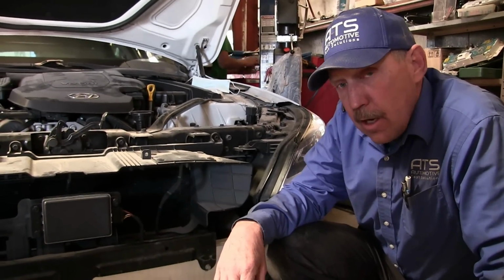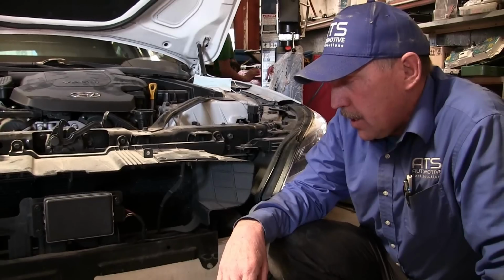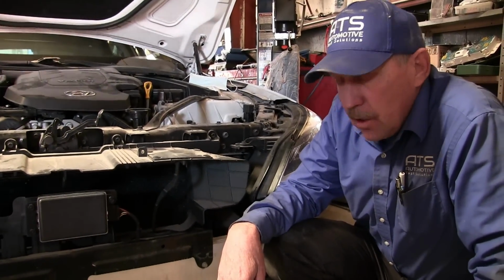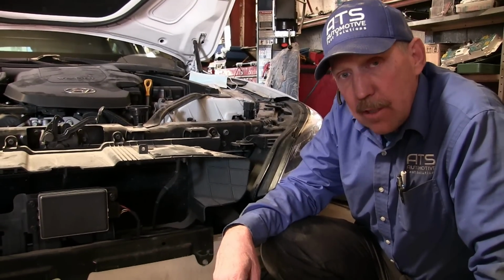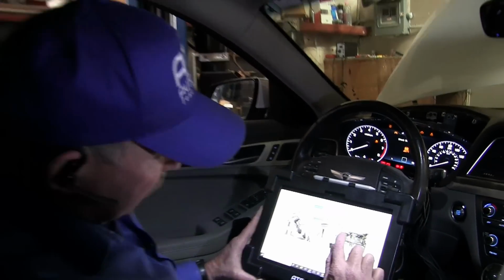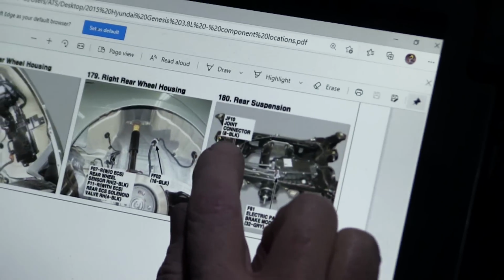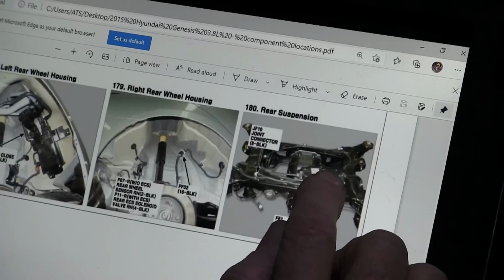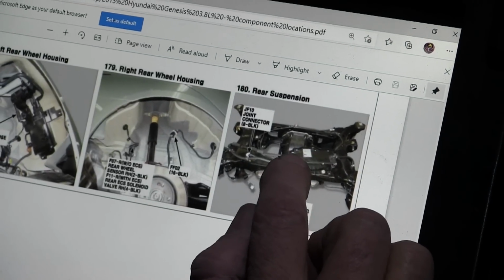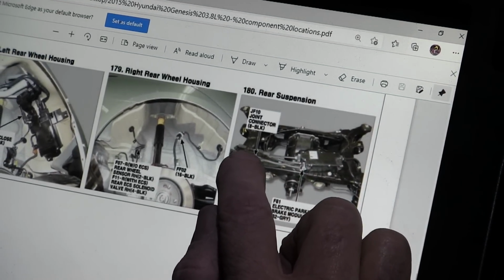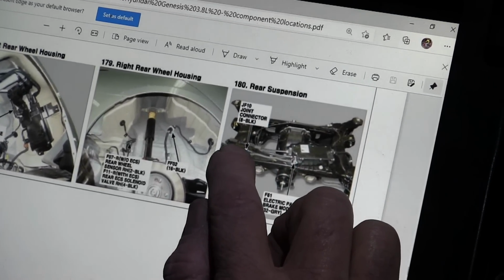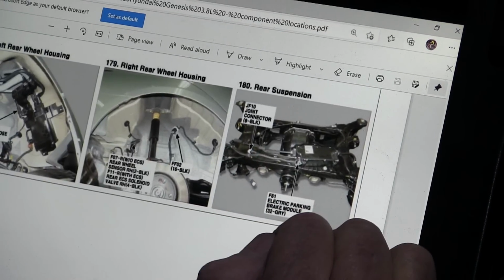The radar is not my problem right now, so let's go ahead and find that other connector wherever it is, so I can separate that portion of the bus to see what's going on. Okay, I've found the other connector, and it's right here, this JF10 joint connector. You can see right here, this module, that's the rear parking brake module. And then we've got a brake off, and we can see that this connector is right on top of the subframe. So that's the connector that I need to go find under the car.